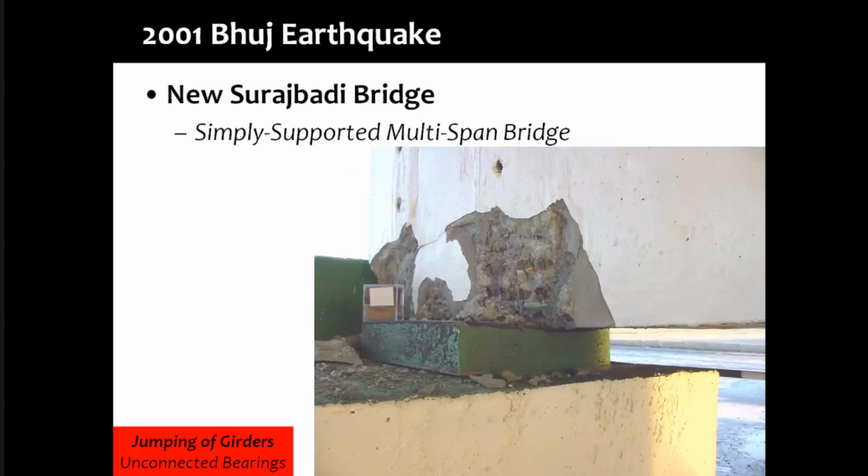Another practice that has to be discontinued urgently in this country is the use of elastomeric bearings without the end plates. We have done about 4 or 5 decades of this. Let's just plug out of this. This is not acceptable in seismic design. If you want to put a bed block, put a recess in that and throw the pad in there, and at the soffit of the superstructure girder, make an undercut there, and then just try to adjust the two one on top of each other. That was old day bridge engineering. The modern bridge engineering does not allow such laziness in the process, especially for bridges in high seismic regions.